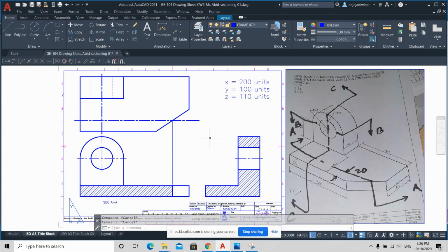Okay, is everything clear until here? Yes, everything is clear. Okay, so the final cutting is BB. We will cut this object at BB. So your knife, your plane will be in this direction. It will cut from front to the back, and then your eyes are pointing downward.